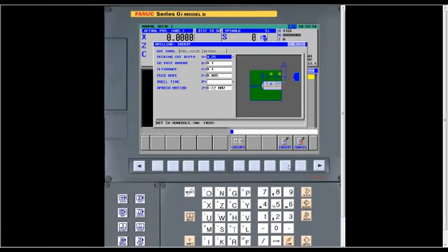It shows a picture of what it's doing, and it has the Q highlighted. The first thing it asks for is a pecking cut depth. We're on cutting conditions for drilling, and you can see next to this it has an asterisk. Anytime a cycle has a field with an asterisk next to it, you don't have to answer that information. It's optional. But in the example I have here, I did answer that part of it.